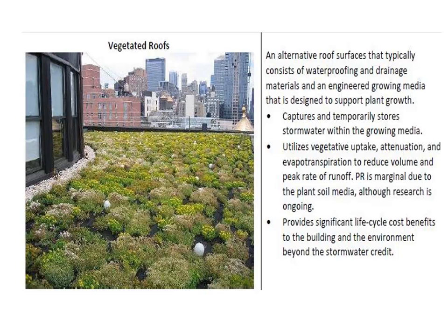A vegetated roof is something that, like all of these measures, is trying to promote infiltration. Except that you think, what's underneath the vegetated roof? It's offices, it could be a hospital, it could be classrooms. And so you have a little bit of a dual mission: you want to keep water out of the building, but you want to promote infiltration in a layer that's above the ultimate water barrier in the roof.